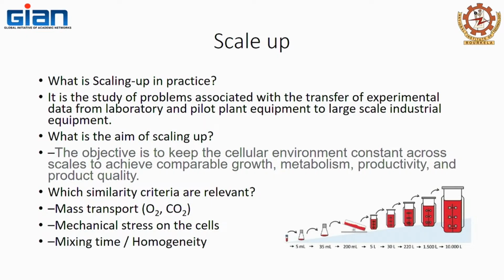All of those parameters have to be transferred if you are moving from a small fermenter to a larger fermenter. Your OTR and OUR have to be maintained. Your removal of heat has to be maintained. The agitation speed that you were using in a smaller fermenter might not be the same in a larger fermenter. The amount of power input for that agitation will differ on a larger fermenter. So, all of that power ratio has to be maintained when you are looking at scale up.